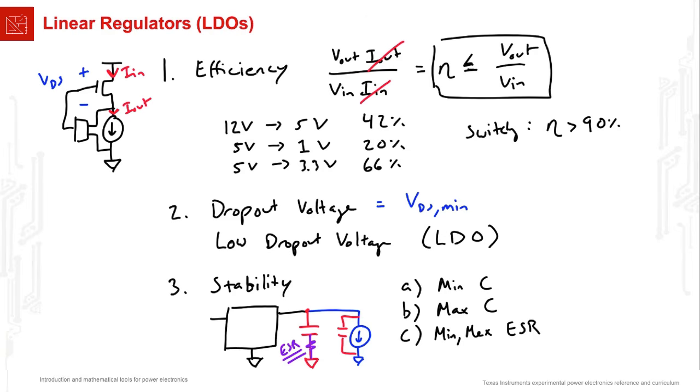And we don't have time in this video to go over all the little details of it, but it's something to be aware of, that some LDOs actually want the capacitor to have a reasonable amount of ESR, in which case you might use a tantalum capacitor instead of a ceramic. My solution to this problem? Simply look for linear regulators that explicitly say in the datasheet, stable with ceramic capacitors. Many modern linear regulators are like this, but I always look for a phrase like this when I try to use LDOs. It just makes your life a lot easier.